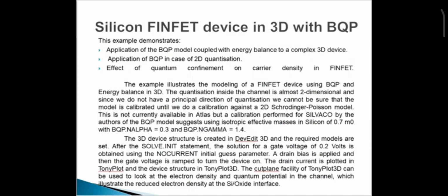Silicon FinFET device in 3-dimensional with BQP model. This example demonstrates application of the BQP model coupled with energy balance to a complex 3D device. Application of BQP in the case of 2D quantization. The structure is shown as 3D, but the quantization is actually in 2D mode. Effect of quantum confinement on carrier density in FinFET we will discuss. This example illustrates the modeling of a FinFET device using BQP and energy balance in 3D.